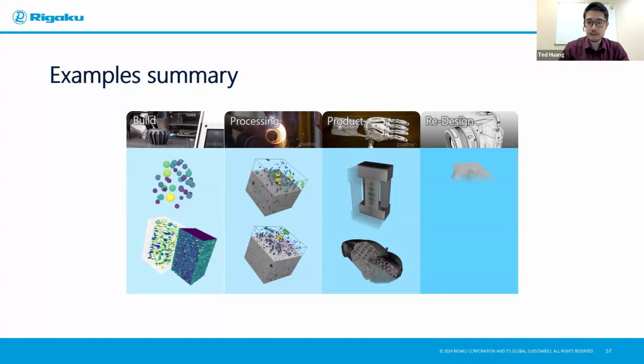And with redesigning, I was able to do a nominal to actual comparison and some dimensioning for the fat polarized model, and also for load distribution analysis, did a principal stress distribution analysis on the car model. And with that information, you'll be able to redesign your CAD drawing and then put it back into the 3D printer you're using, and then move on to the next iteration.